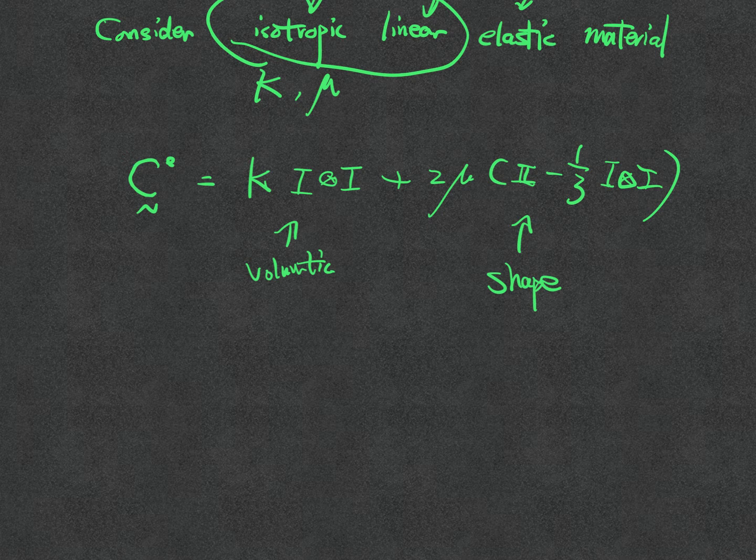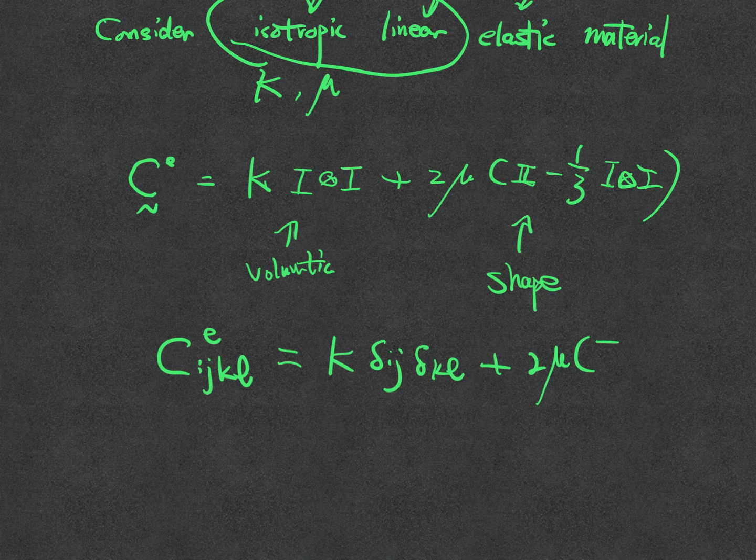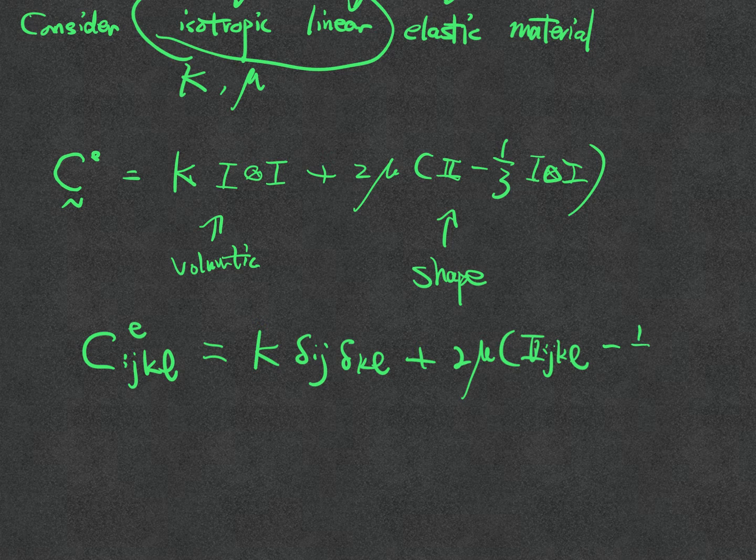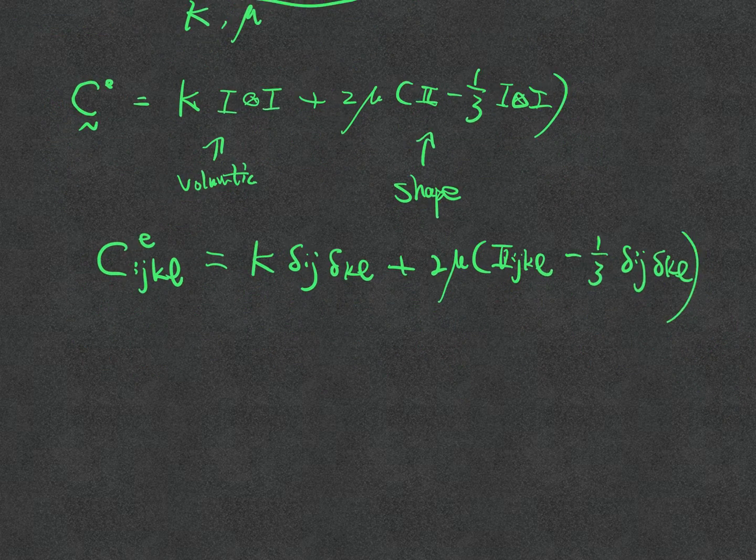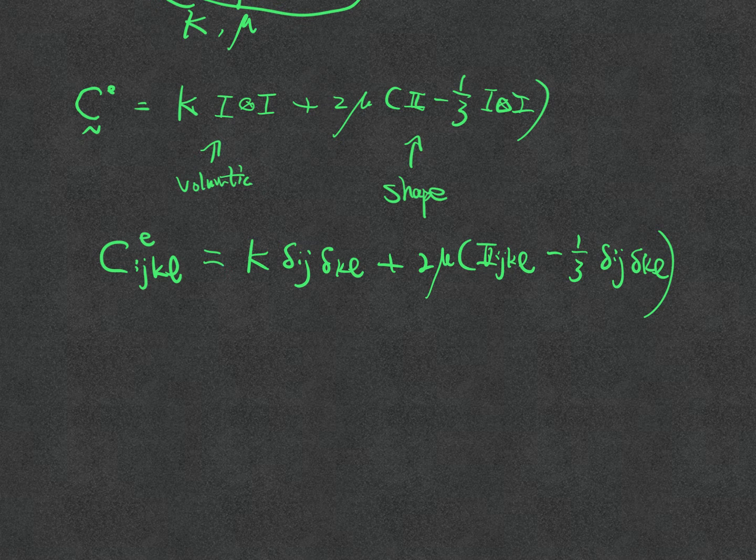And a lot of the time, this is a good enough assumption. Except if you want to model biomaterial, then I never recommend you assume something is isotropic. Or something that has texture like wood. That would be a terrible idea, to model timber as isotropic material, for example. So again, I'm just trying to practice my Einstein notation skill using this. Okay, so far so good. Now, this is actually the linear elasticity tensor.